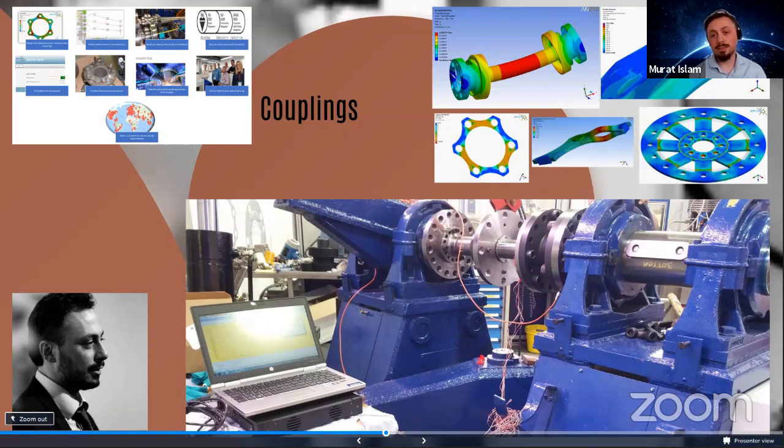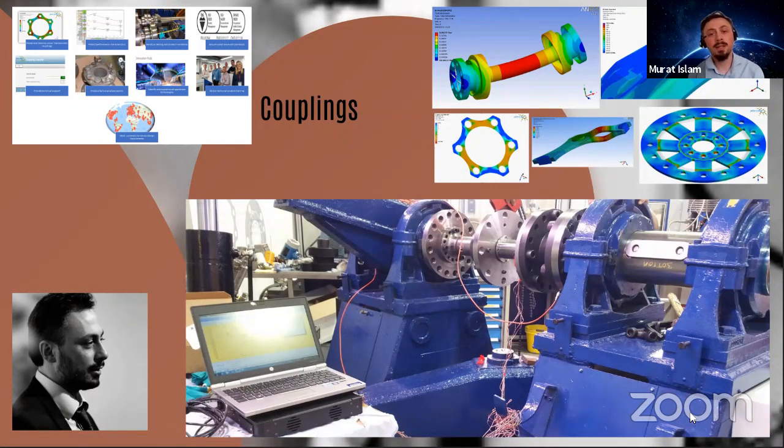that we have. This rig actually applies pure torque on the coupling. There is no axial force, there is no lateral force. All we are doing is moving two lever arms to create pure torque in the system. And for that, you then actually measure what the stress level is on the spacer tubes you are using. And if my coupling has some membrane shapes built in them, which I can't go into much detail on here, how are they impacted by this? What sort of deflections do I get when I put certain torque values through my system? So we have to run various performance tests, and that requires understanding the materials.